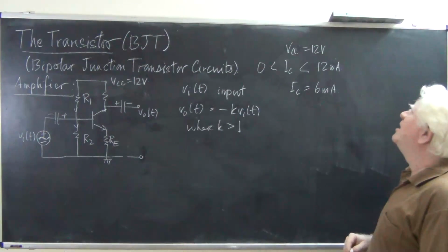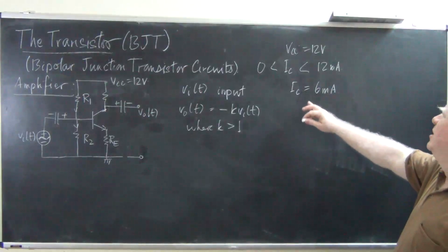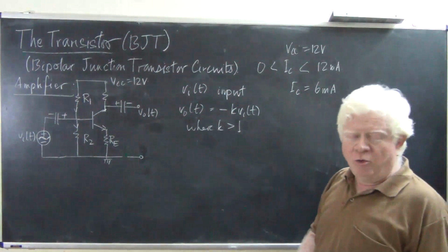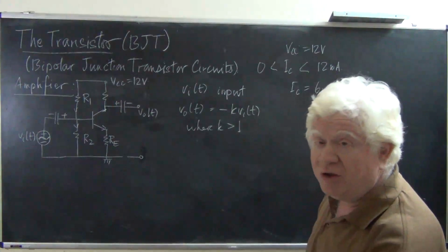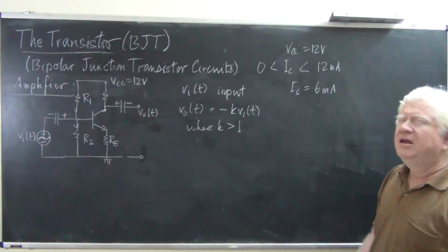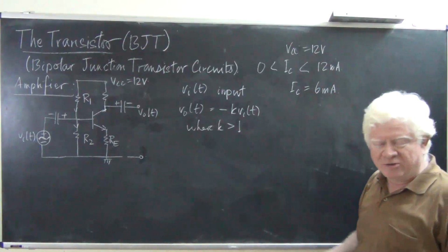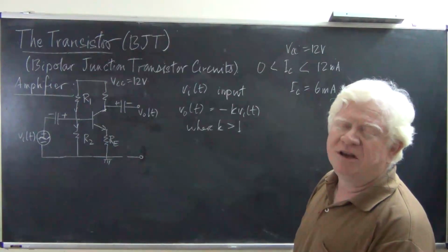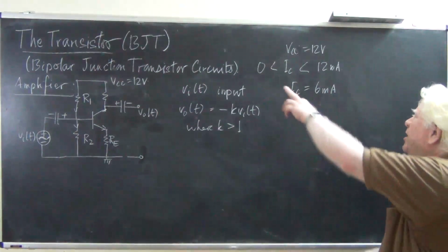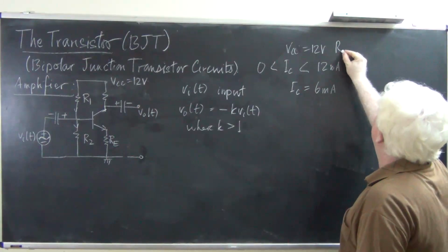When it is 6 milliamps, this flows through our 1 kilo ohm resistor. Actually, the handout will tell you what other values of collector resistor to use than the ones I am describing here. The purpose of this presentation is to make the calculations simple. You will be using, according to the handout, a 3.3 kilo ohm collector resistor, and you have to make your calculations accordingly. But for the 1 kilo ohm resistor that we had in mind, these are the appropriate calculations.